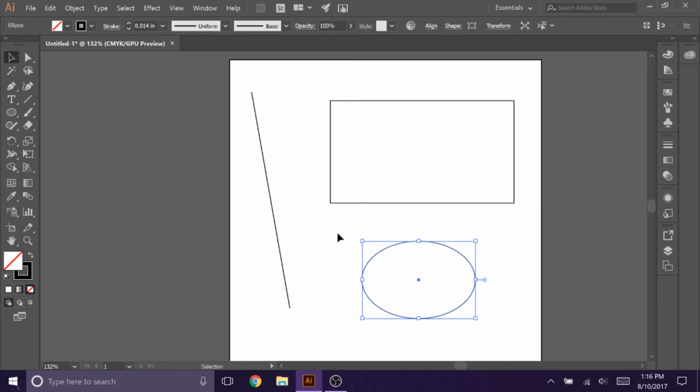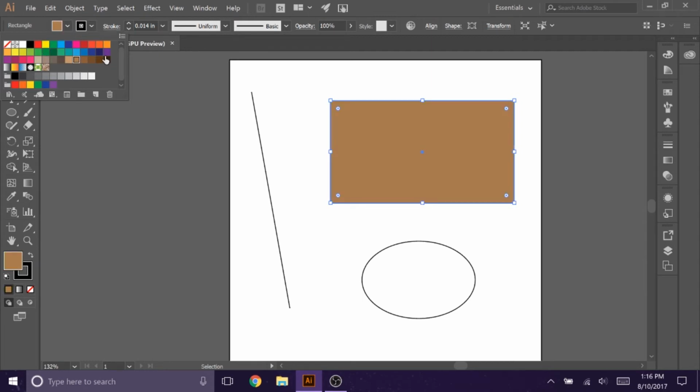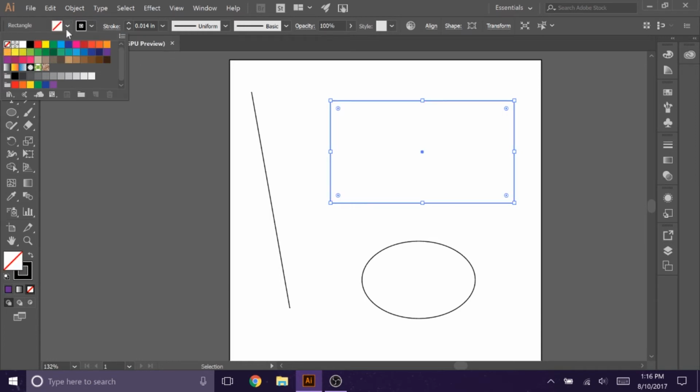Once you've created paths, you can assign attributes to them. If you select one and go to the top left corner, you'll see these two drop-down boxes. The first one is Fill. That determines what color the interior of your path will have. You can really set this to anything you want it to be. However, for the purposes of cutting, you probably just want it to be transparent.